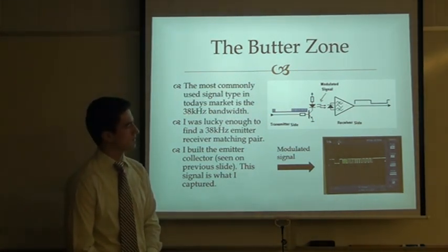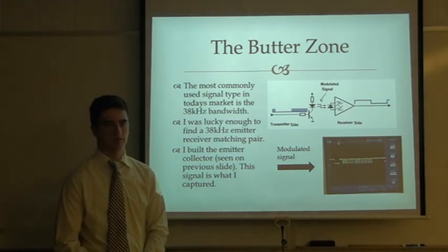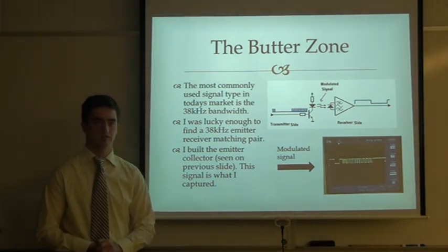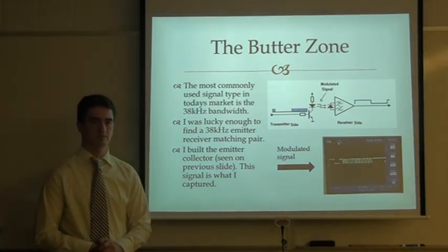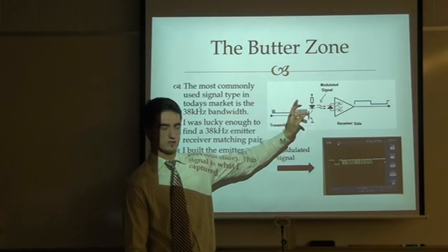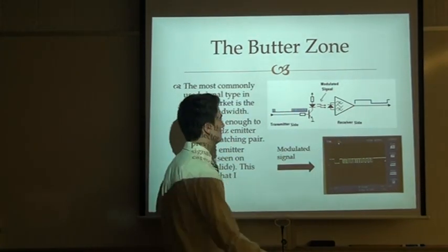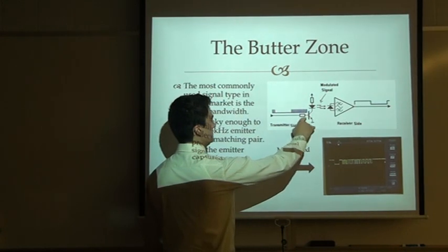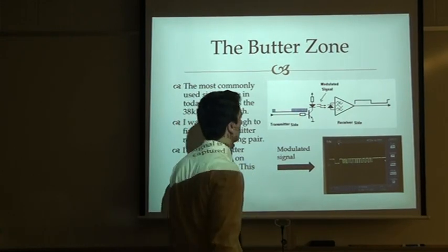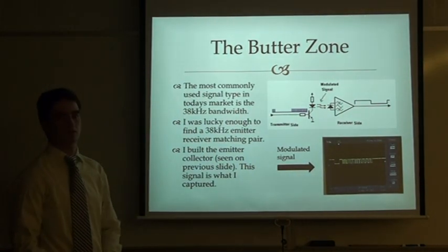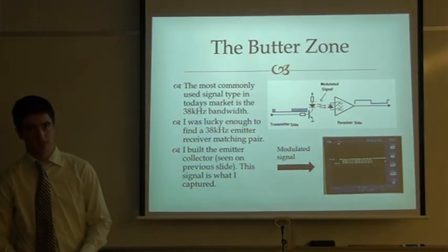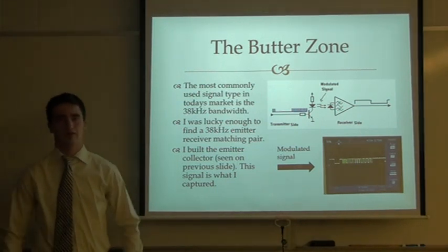Right. Okay. Because the pin diode wouldn't filter that signal, it would just show the undemodulated signal. This would be the modulated signal. This is demodulated, I think. Oh wait, no, I'm getting these backwards. Demodulated, modulated. Yeah, that makes sense. Well, you have it labeled in the middle. The modulated signal that's in the middle, right? So the modulated signal has the overall shape of the data you're trying to transmit, but it's being created out of these 38 kilohertz pulses.